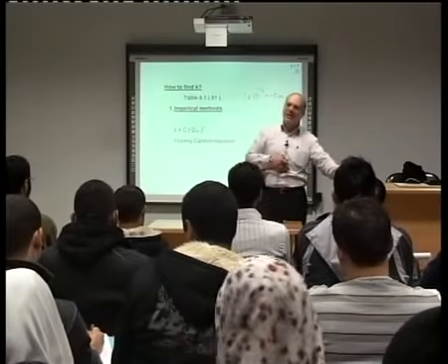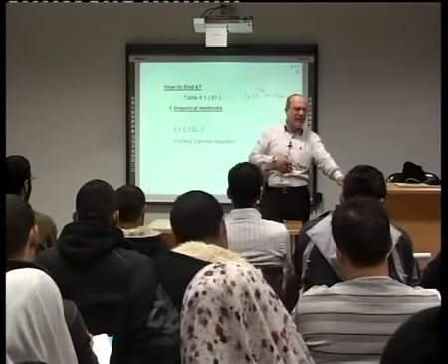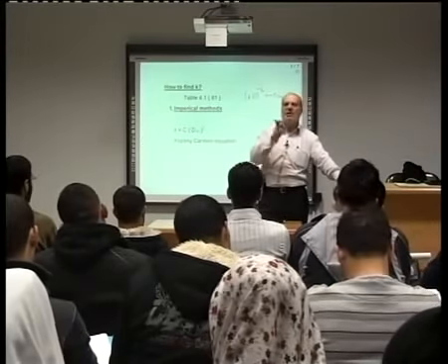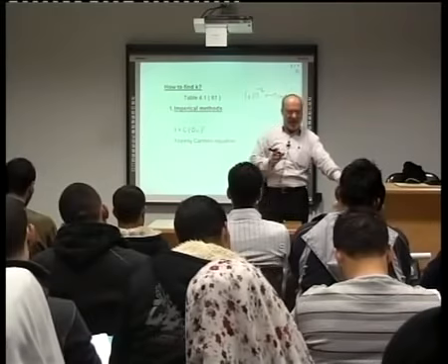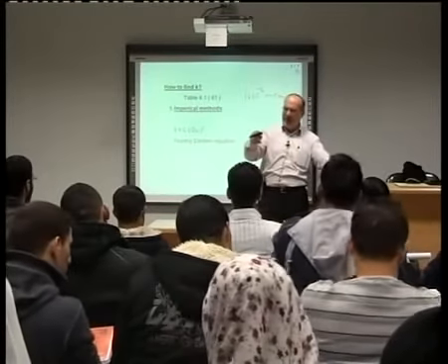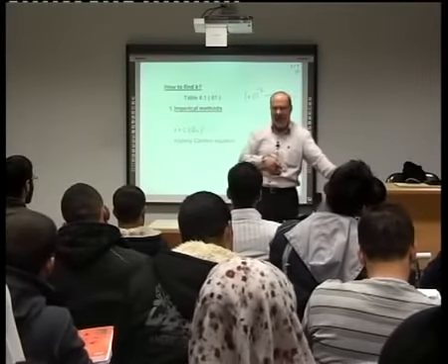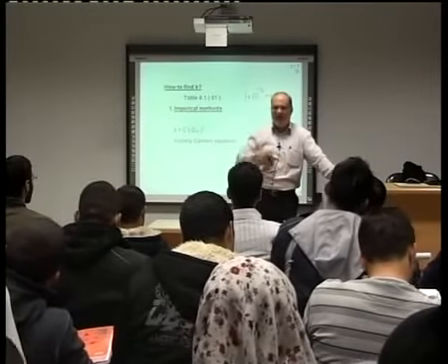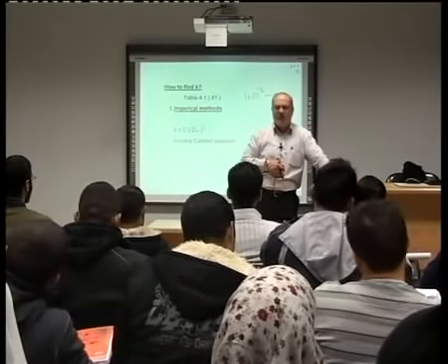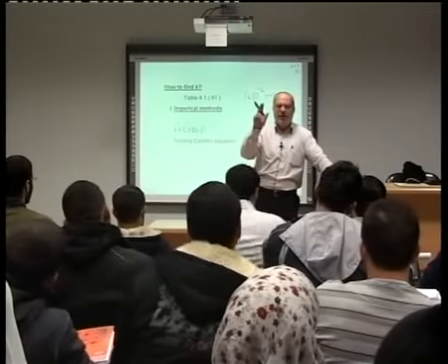If you are designing a dam, a water tank, a pool, a basin, if you are designing anything that relates to water, then you have to do a permeability test. By the way, permeability test is your test after compaction. Okay, you will do it in the lab here. Okay, you will do it in the lab. Now, how to find K? Three main methods.